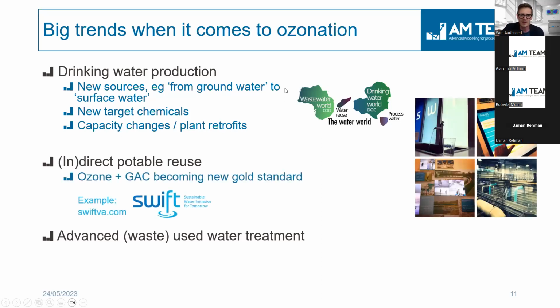When you look at indirect or direct potable reuse, ozone plus maybe activated carbon adsorption is becoming a new gold standard. This means in the past it was all membranes, RO, very tough, or very strict multiple barrier concepts. Well, ozone is really emerging. Look at SWIFT, for example.